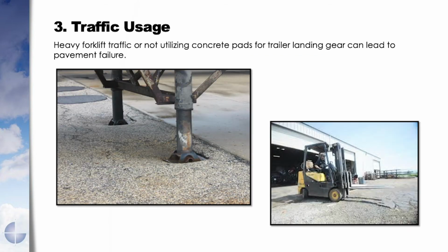Concrete usage for traffic. The photograph on the left was a project we had where the project was built when we had shorter semi-trailers, and then the longer trailers came out, and now the landing gear don't sit on the concrete, causing failure of the asphalt pavement. What we did here is we extended the concrete out, so that the dolly pads now sit on concrete, because obviously filling in the divots with asphalt like they did in the background did not work.